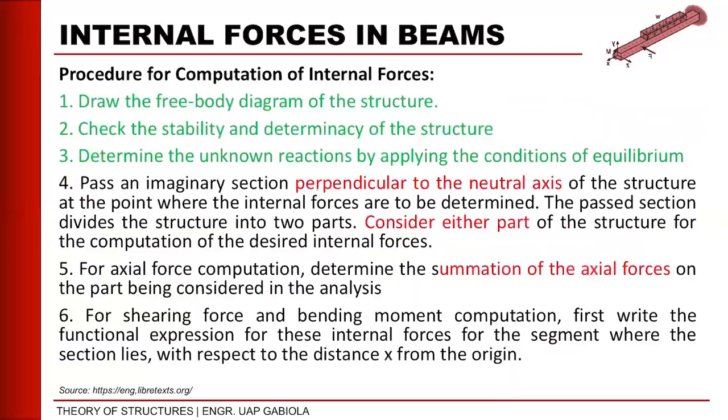Then now, we go to sa procedure for computation ng internal forces natin. So, ito daw yun. First is draw natin yung free body diagram. Marunong na tayo niyan. Number 2, check natin yung stability and determinancy of the structure. So, marunong din tayo niyan. And sabi ko nga nung last session natin, we can only use the equilibrium equation once our structure is statically determinate. Okay? Pag statically indeterminate siya, we need additional equation like the compatibility equation to solve for the reactions. Pero we will not discuss it yet. Okay?